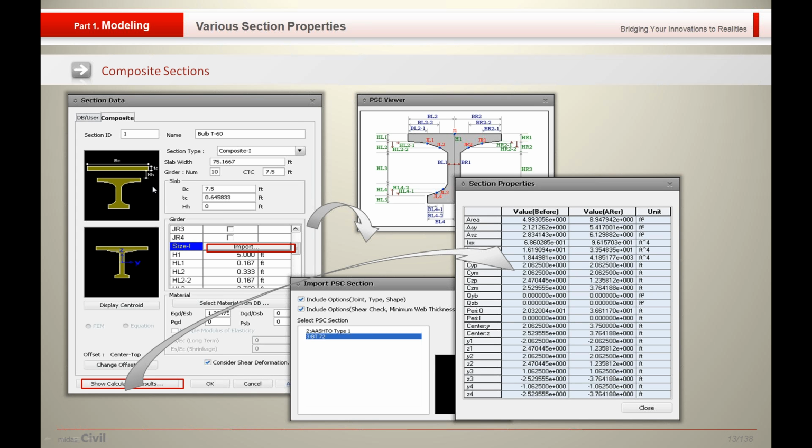Okay. So also you can control, like in composite sections, usually the problem that we face is that while doing construction stage, we first define the girders over the bearings, and after some time we lay the formwork for the slab, then we pour the slab over the formwork. Even when the slab is present in its wet form, we do not consider the composite action there. So we consider the composite action only after the slab attains its green strength.